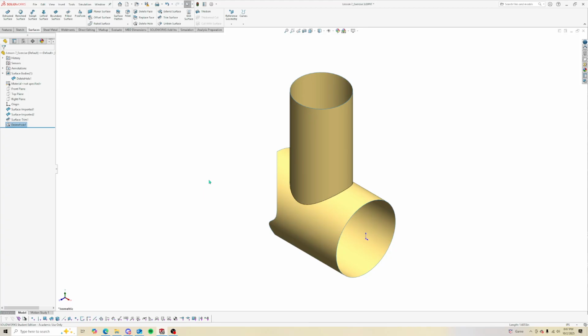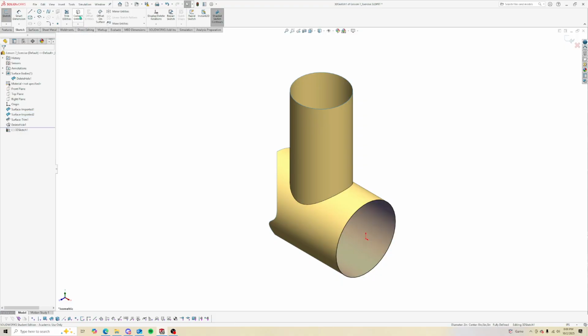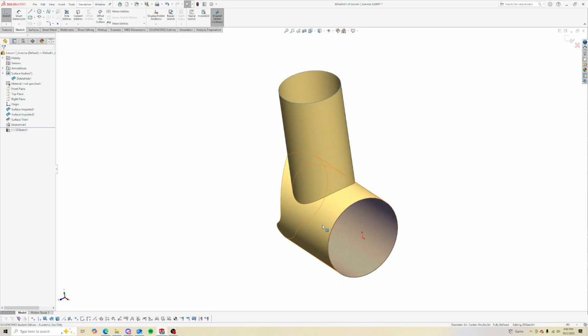So now you're going to create a patch on a broken surface. Patch up the broken surface. But for this, we will take a look at filled surface and extruded surface. Open a new 3D sketch below. Here, sketch, and that drop down is going to be 3D. Select the circular edge on the right and click convert entities. So here and convert entities, or just this right here. So now you have that black, fully defined hole right there.